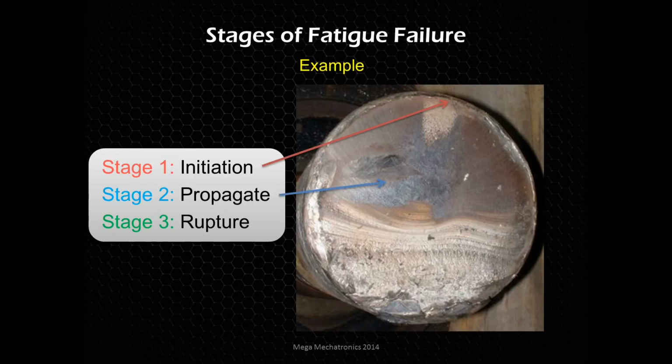Look at that rust, that oxidized orange, dark brown surface. So you can almost tell that this has been propagating for a while. And then it gets lighter and lighter until we rupture down here, where we see sort of a brittle fracture. And we can make out how far those beach marks made it to that final point. So it almost went through three quarters of this shaft before it finally failed.